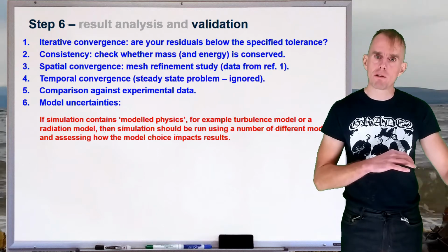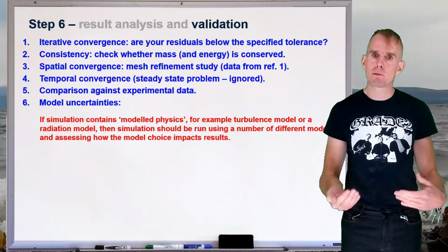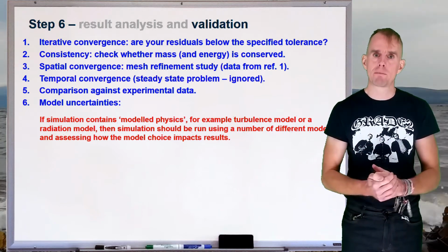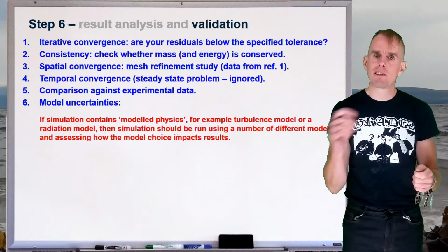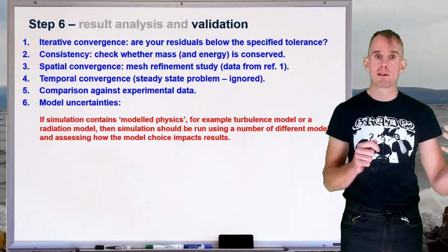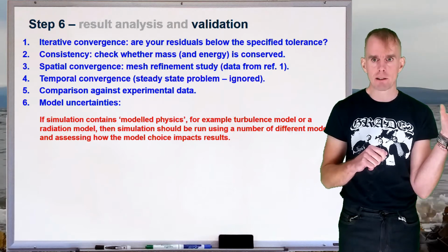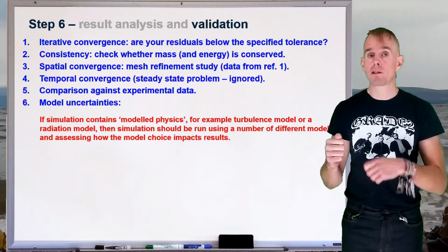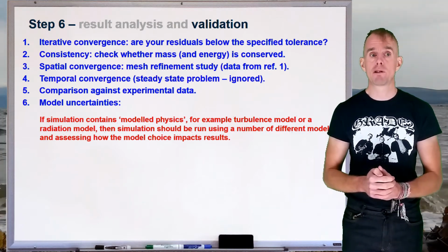This might be important if you have a coupling between your viscosity and your temperature. Typically, fluids become less viscous with increasing temperature. And so if there's uncertainty around a material property, do a sensitivity analysis on that to see how it affects your results. It may not affect your results at all, in which case you can prove that your simulation is insensitive to that, or it may have an effect far beyond what you could have ever imagined, which may pose some very, very pertinent questions about how you proceed.